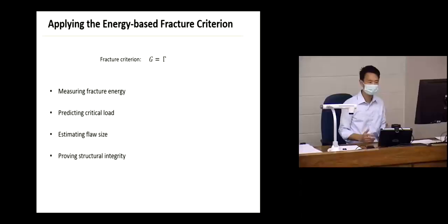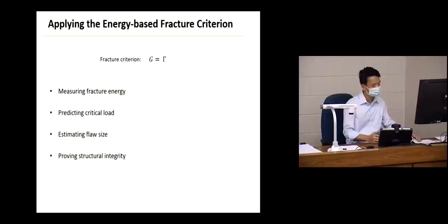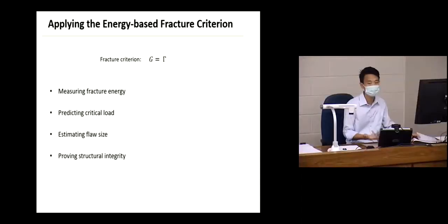And so if my ceramic, the solid oxide fuel cells, has a crack size larger than that, then it's no good. So this becomes my design goal. I have to go to the manufacturing process and say, please make me this solid oxide fuel cell material that has a flaw size smaller than 5 microns, right? So there are ways of doing that, right? By more careful processing, you can change the flaw size.